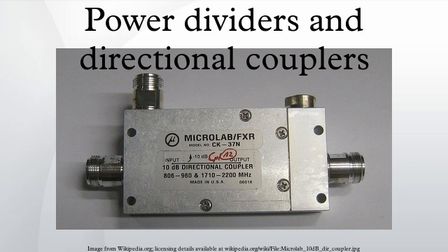6 dB resistive bridge hybrid. A true hybrid divider coupler with, theoretically, infinite isolation and directivity can be made from a resistive bridge circuit. Like the T circuit, the bridge has 6 dB insertion loss. It has the disadvantage that it cannot be used with unbalanced circuits without the addition of transformers. However, it is ideal for 600 Ω balanced telecommunication lines if the insertion loss is not an issue.